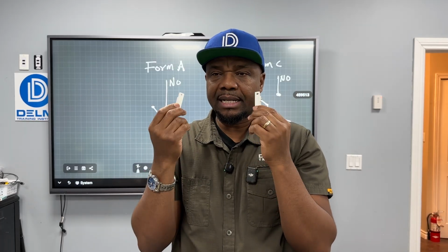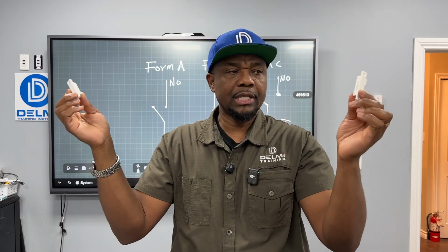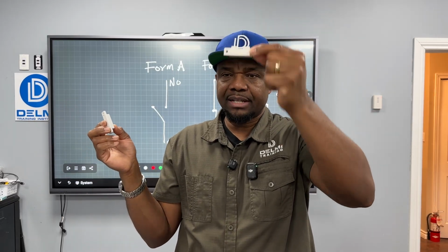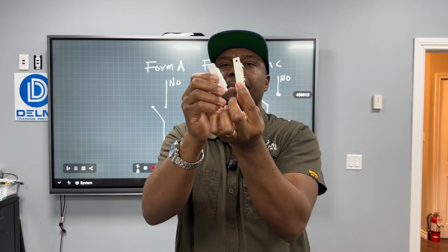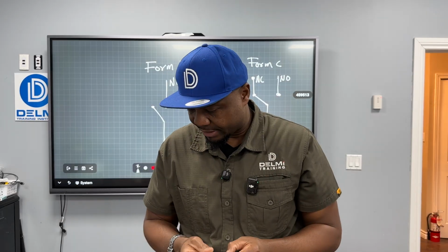The ideal and the normal state is when they are apart. So when you want to test the default state of this, don't put the magnet close to it before you test. Keep the magnet away and test it. That will tell you what the state is in.